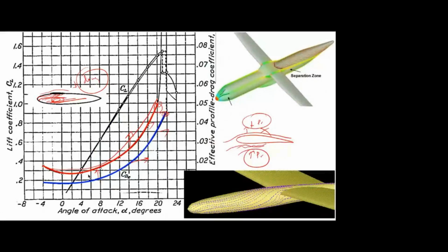But if you go for designing of aircraft, we don't see only the aerodynamic properties. We have to see structural considerations, economical considerations, everything we have to take, even performance parameters. So if you go for the high wing, the drawback is that the structure beneath this wing should be very strong to withstand the wing weight. Okay, so we have to add more structure, that means more weight. So unnecessarily it increases the complexity. Okay, unnecessarily we are increasing the weight also. So mostly we are not going for the high wing. High wing configurations we will go for only the cargo type. Okay, because cargo means the total weight will be very high.